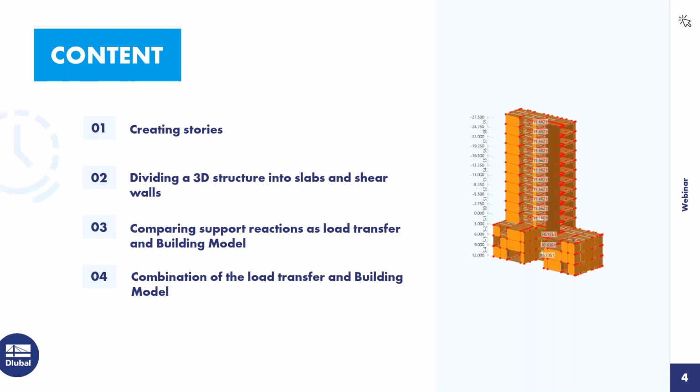So the nine stories on the top are smaller than the 3 stories in the bottom, and therefore it is, in my opinion, the best way to analyze this bigger cantilever or balcony outside with this bigger area with the 2D analysis. And in this way I can combine 3D and 2D calculations.